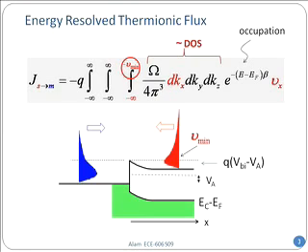But there are many organic semiconductors that people are using for displays these days, which have a very tiny band distribution or bandwidth. In that case, putting the right limit, not minus infinity, would be the right thing to do. Okay, but what about Vmin? Well, Vmin is essentially talking about the fact that unless it has a minimum amount of velocity or minimum amount of energy, an electron going there will be bounced back by the barrier, and as a result it cannot contribute to the current, and it should not be included in the flux. So that's where the limits come from.